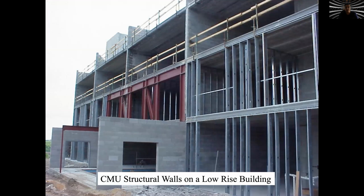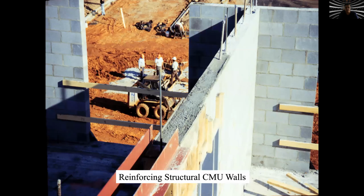Sometimes the CMU is not even reinforced. In this picture, we have a reinforcement in a part of the building because the span is much bigger. In some countries, on the contrary, it's forbidden to build buildings of more than 1 or 2 floors if there is no reinforced steel inside. Reinforcing structural CMU is made with concrete, and usually in the superior part of the building and in the base of the building, you will have an area with concrete and steel, also as columns, to make it stronger.